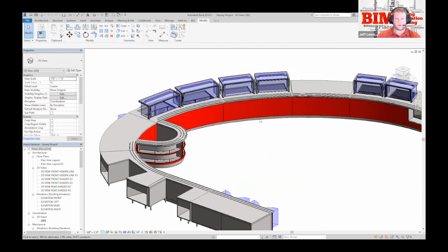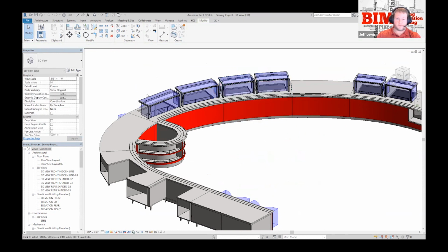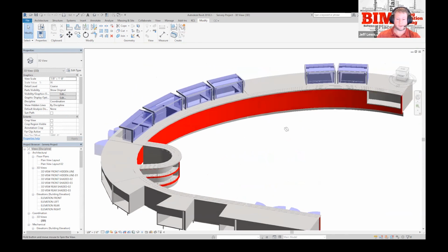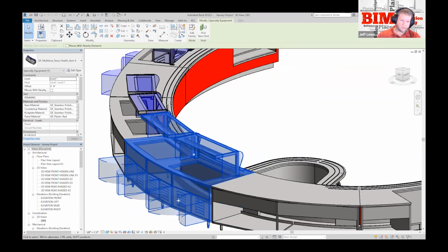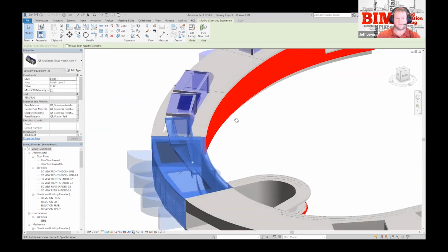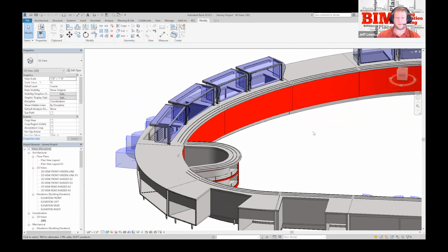Now let's go into a curved piece. We also notice on this here is most of these sneeze guards are pretty much the same. Those you would want to build as nests. This is where the upfront planning comes into play. You can build those first, come around, and in my case, I built the doors as a nest because they were going to be used in multiple places. When you build a nest, the more it's used in that same project, the less space it will take up.